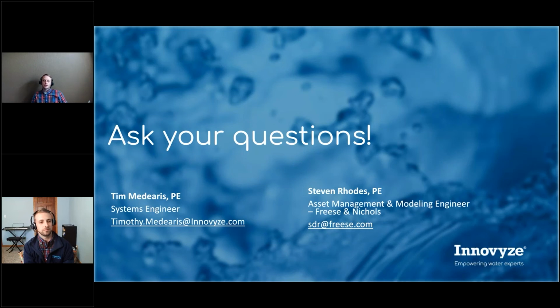And so it either wouldn't initialize or it would, and then we would get crazy model results because the basins were already half full, and then they would overflow. Just working through that logic, I think I got in touch with someone at Innovyze to help me understand how you can define those RTCs so that those gates will be open during initialization and closed in the simulation. I didn't realize that you could do something like that, but it worked out well.